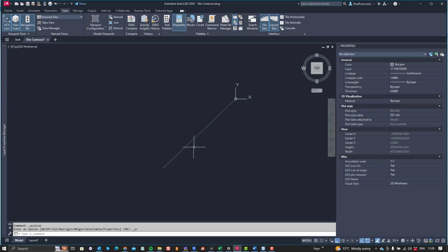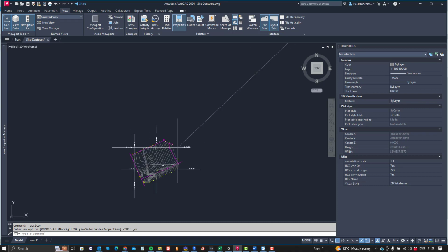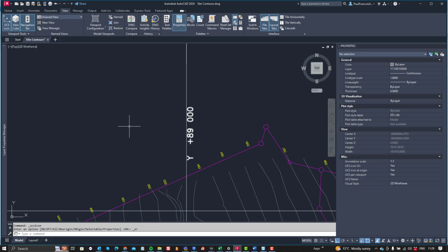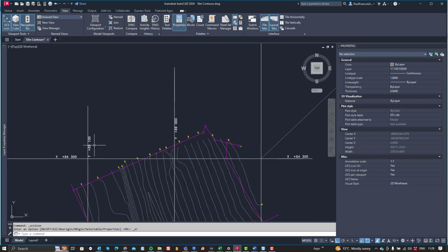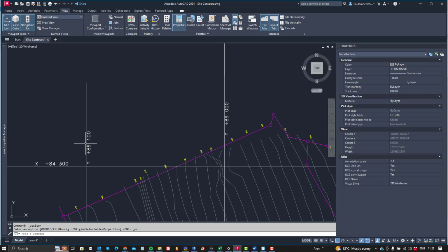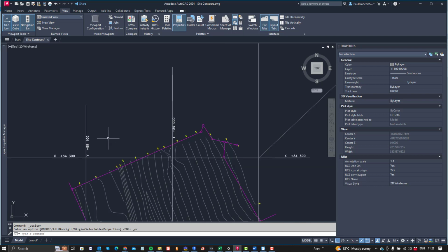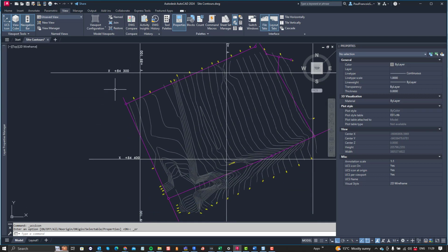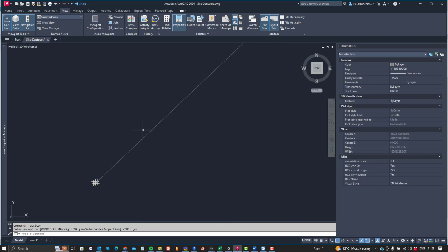But note that because we're in the southern hemisphere, looking at the easting and the northing numbers, we are increasing going towards the left, and this is designated as Y. And then similarly in the X direction, going downwards, we are increasing going down. So basically what they've done is, in South Africa they map X to Y and points towards the bottom. So X would be pointing downwards and Y would be pointing towards the left.